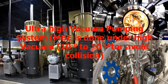Please note that for silicon based molecular beam epitaxy, the ultra high vacuum is even higher, around 10 raised to power minus 10 torr. So this is the key disadvantage, that we require an ultra high vacuum in order to make it successful.